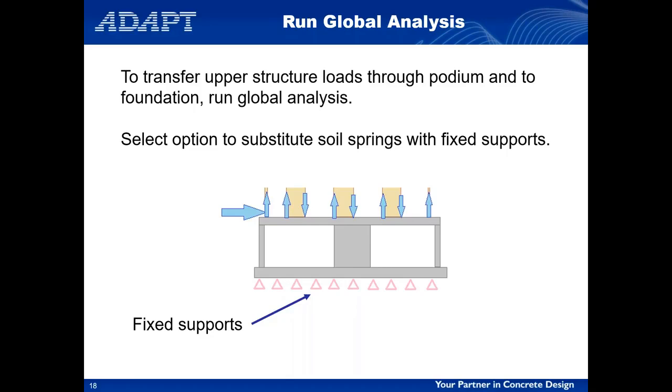So to do that, we're going to switch to running global analysis, and we want to make sure that when we run the global analysis, now remember, we had modeled the soil springs. One thing that catches people by surprise sometimes is if you just go into that analysis, you get the full structure soil interaction, which is great, but you get a lot more flexibility and distribution of the loads based on the actual, full flexibility of the structure.